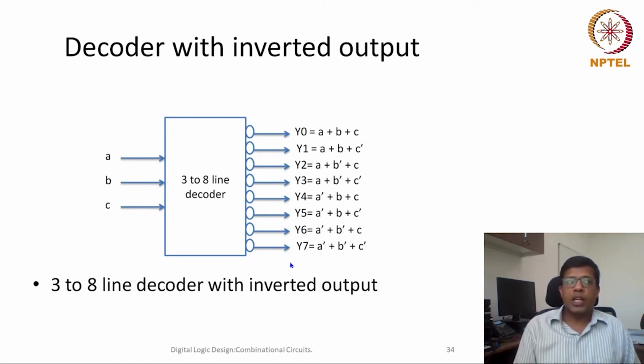Okay, so this is one. The other is in some of the technologies, like we finally all these gates would be implemented like a transistor. So these transistors could be CMOS, it could be BJT, and then there are logic families also, ECL, TTL, etc. So in some of the families, it is preferred that if default output is 1 rather than 0. So some of the chips are fabricated with this inverted output. And this concept of inverted output or inverted input is quite generic.